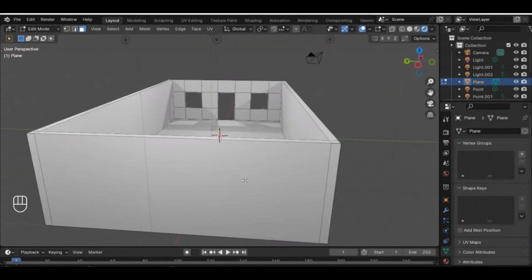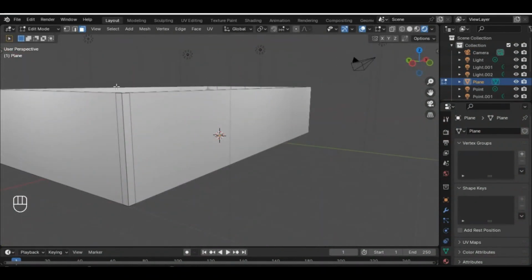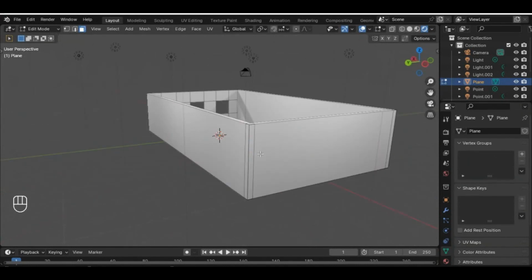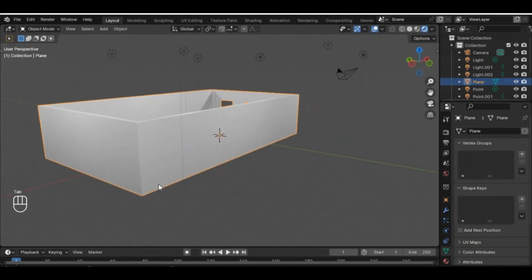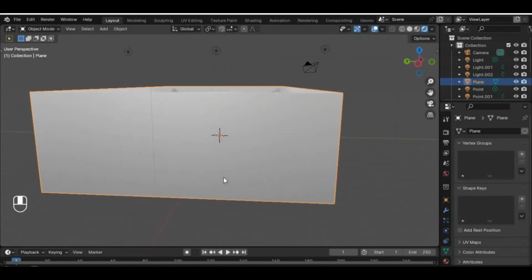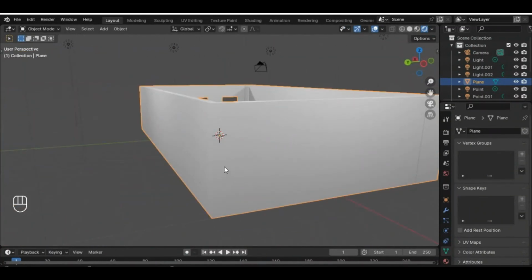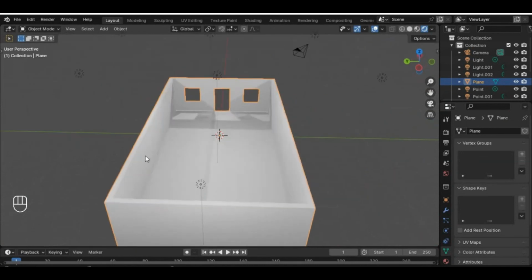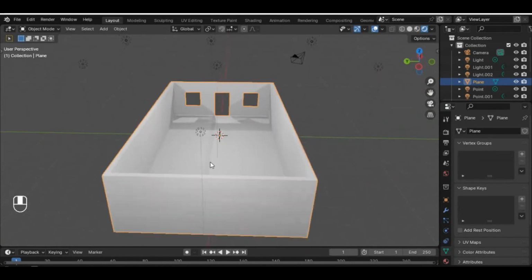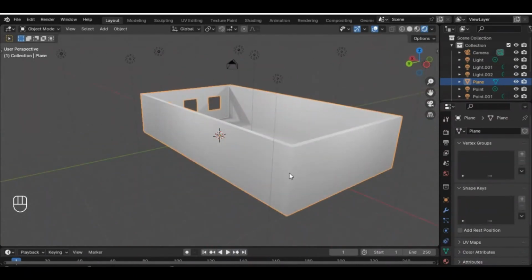Now we have something funny looking here. You see these joints here. I don't really like that. Even if you tab back to object mode, they are not noticeable and it looks like you can easily discard them, but I don't like having them because when you start to do complex editing, like wanting to have partitions here, it begins to give you funny problems. You might have trouble choosing and make unnecessary doubles of your vertices. So I'd rather get rid of them.